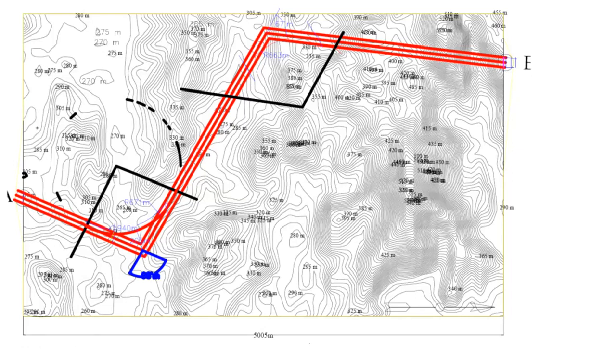An important check, one of the guidelines, is that these two curves must be separated by 100 meters. What I am trying to say, and you must listen carefully, is that the PT of this curve and the PC of the next curve should be separated by at least 100 meters.